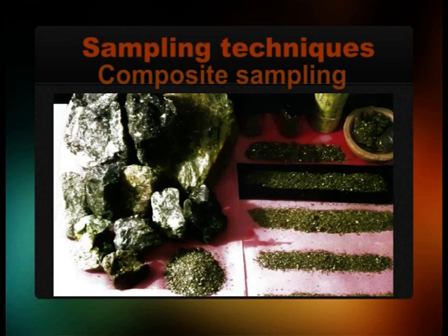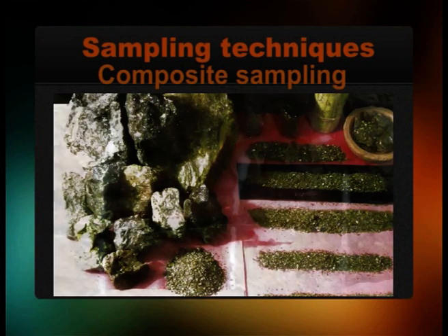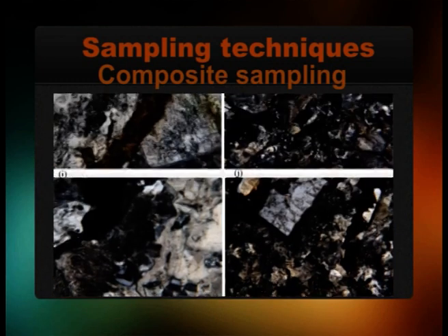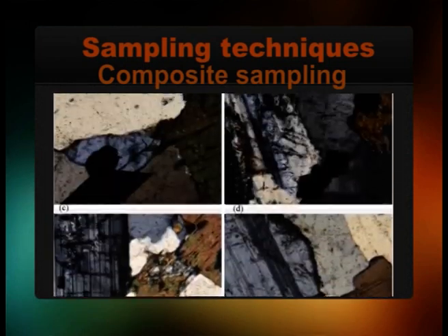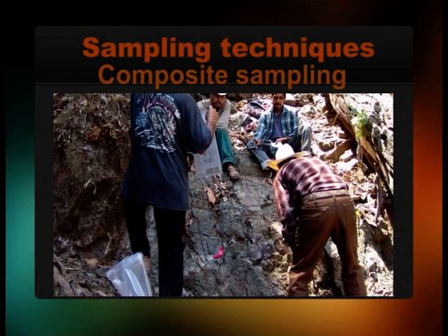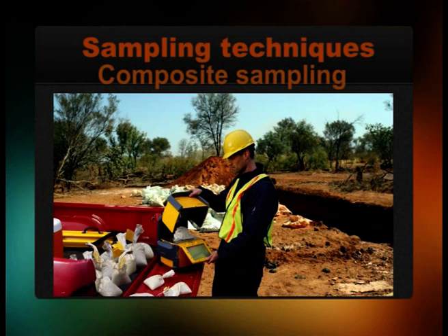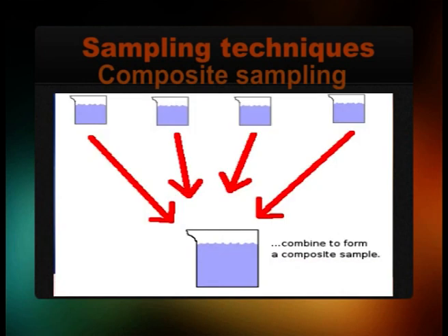Such composites are generally made on the basis of dissolved mineral content as indicated by measurements of conductivity of the daily samples, supplemented by other easily obtained information such as concentration of chloride, river stage, weather conditions, appearance of samples and previous history of the stream.